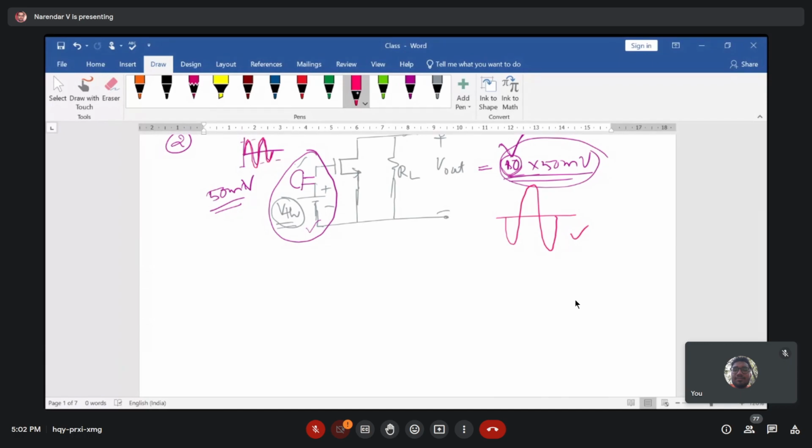From the previous calculation, to design an amplifier, a constant current source, to get 1 milliampere of current, we assumed that mu n COX is 100 microampere per volt squared. Take the same parameters again: W by L equal to 10, and VTH of the device equal to 0.5 volts, right?